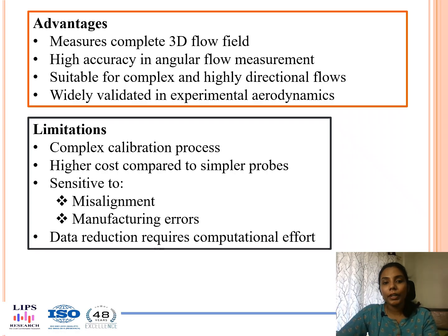There are a few limitations also. Since it has more pressure holes, the calibration process is more complex. Since it measures a three-dimensional flow, calibration must be performed over a wide range of yaw and pitch angles. This is more time consuming, and there will be a high amount of data, which makes the process more complicated.